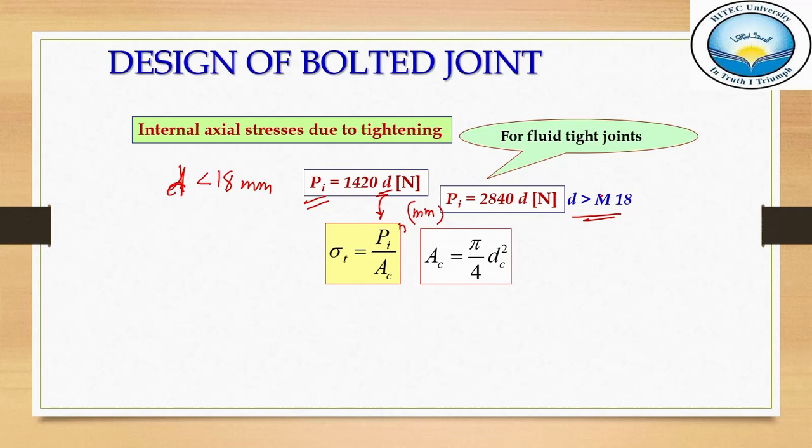So this is the idea, and the stress in the bolts is generally due to tension, and this tensile stress, because it's an axial force, a tensile force, is this load divided by area. Now this area is the core area or the root area. So if you look at the bolt design, we have threads like this on both sides.